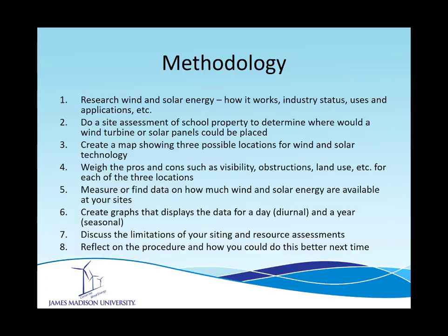Next, you would want to measure or find data on how much wind or solar energy are available at each of the sites, because that will play into, again, which is the best site. And then creating the graphs and display the data that we talked about in terms of a diurnal cycle, a seasonal, annual cycle, your time series, your frequency distributions, and your wind roses.